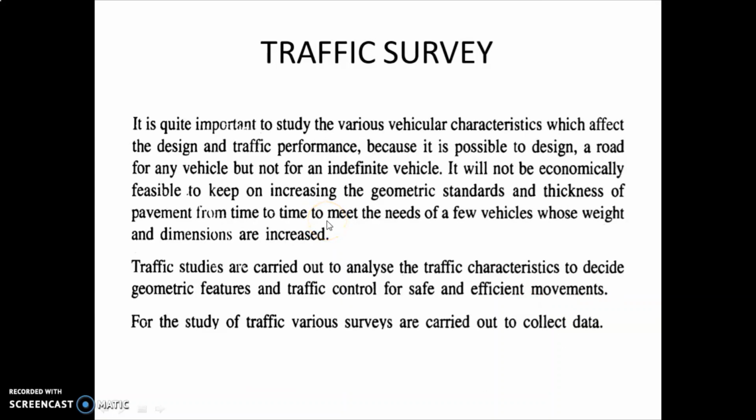Now we will come to the next subtopic, traffic survey. So what is that? It is quite important to study the various vehicular characteristics which affect the design and traffic performance, because it is possible to design a road for any vehicle but not for an indefinite vehicle. It will not be economically feasible to keep on increasing the geometric standards and thickness of pavement from time to time to meet the needs of a few vehicles whose weight and dimensions have increased.